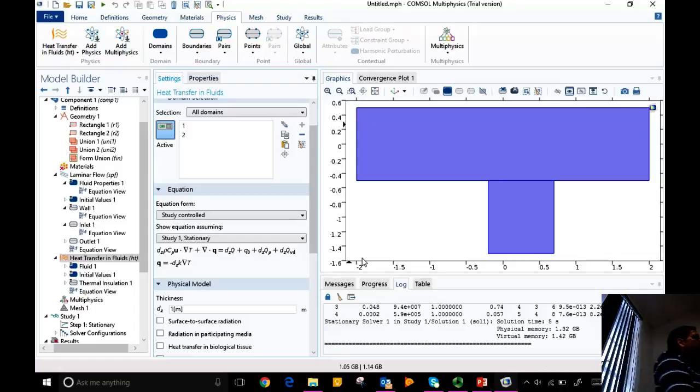Of course, you need to specify the appropriate boundary conditions on all those boundaries, temperatures or heat flux. So you need to know the transport phenomena well to be able to specify appropriately. So we can run a flow in the first rectangle and see the temperature profile of a heated distillate. Because one is a fluid flow and one is a solid, you can have that.